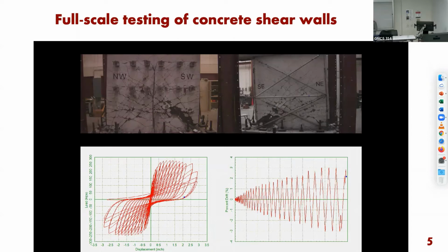Sure. Would the loading be in a different direction if the wave of the earthquake was traveling in a different direction relative to the wall? I would imagine walls flapping back and forth out of plane. Depending on the earthquake, the direction of the wave may hit the building. So the wall is just a component of a building. It may hit the whole building at an angle, and this can create two waves, basically, maybe one longitudinal, one orthogonal, right? You can decompose it. So the one that would be in plane would be like this one. And then there may be other effects.